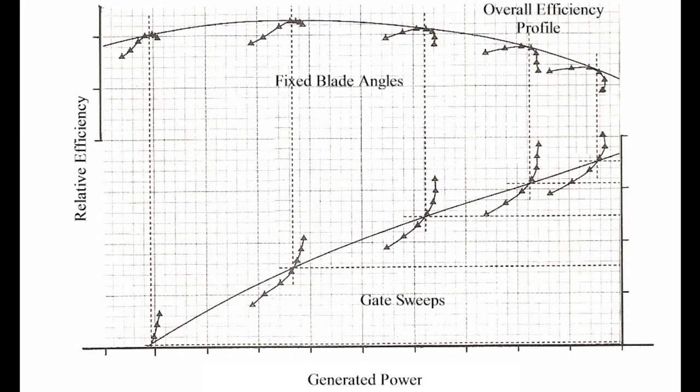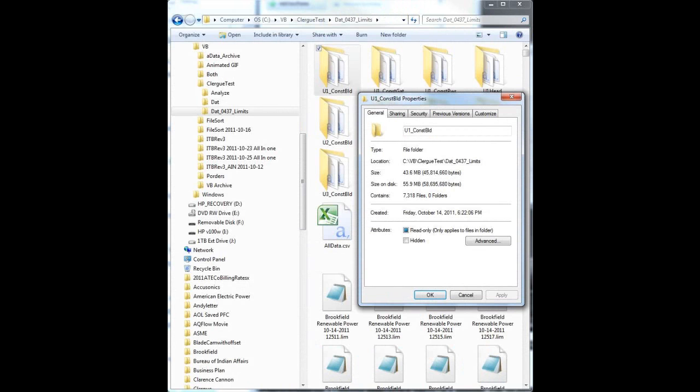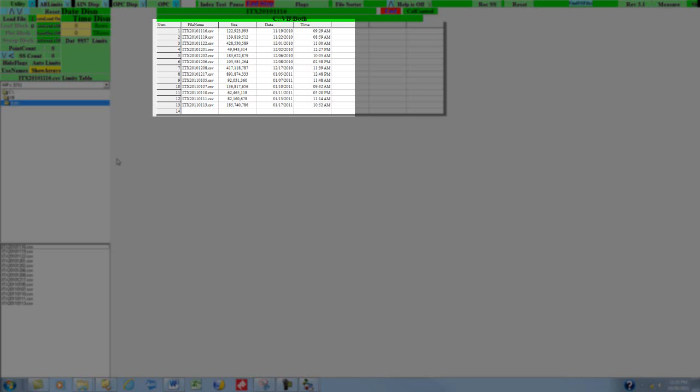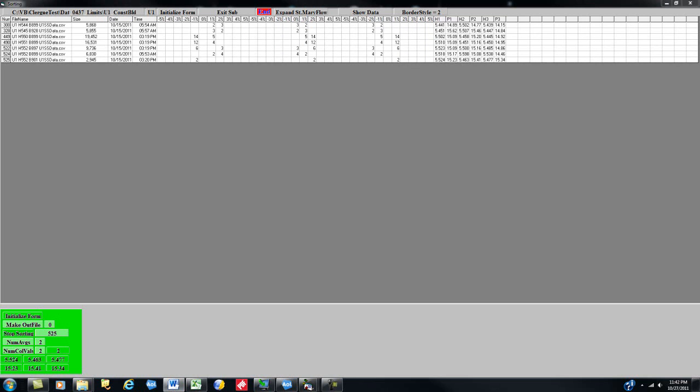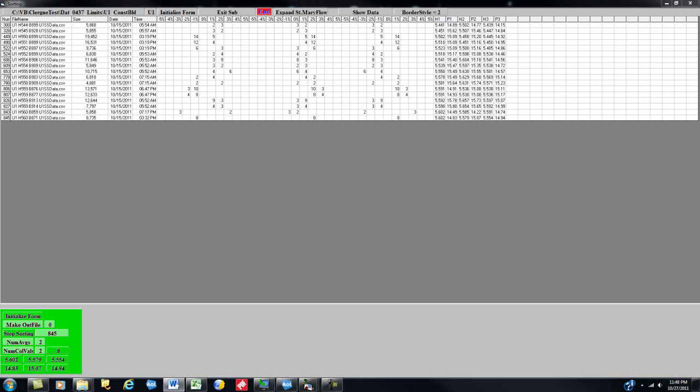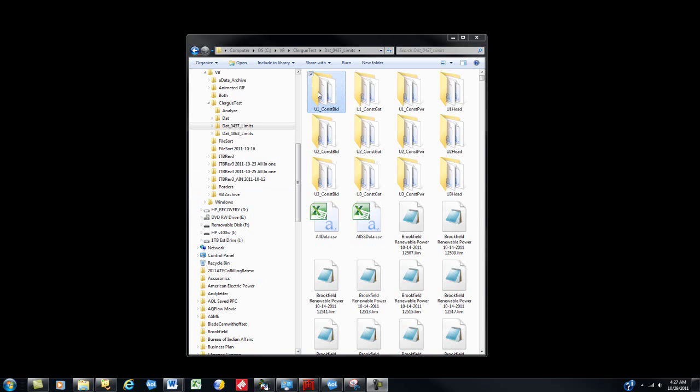This demonstration will use the constant blade test, which is the most common method for Kaplan turbines. For greater simplicity, our method uses gate stroke as the x-axis. This doesn't make a great difference because Kaplan turbine suppliers strive to get gate opening and generated power to come out proportional and linear with gate stroke. The steady-state algorithm has gleaned over 7,300 steady-state points from the 2 months of off-cam data. The second sorting program opens each of these files and sorts the steady-state points contained in them according to their blade offset values. A minimum of 2 data points at 2 or more offset values are required in order to pass this second sorting test.